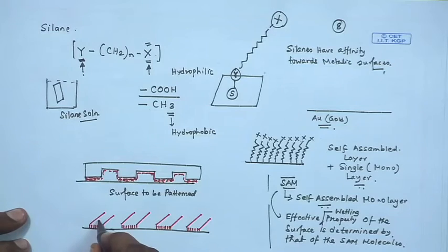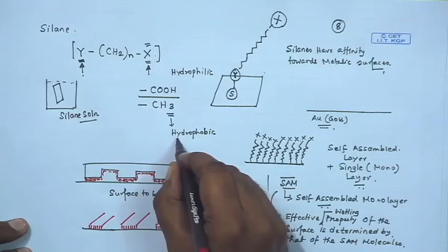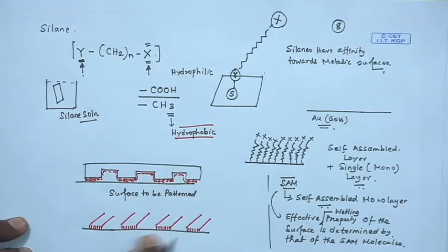Whether these silanized patches are hydrophobic or hydrophilic will depend on the nature of the silane molecule you are using. So, if you are using, let us say, a hydrophobic silane on a hydrophilic base, you can create a surface with alternating wettability domains. You can also start off with a hydrophobic surface and take a hydrophilic silane to achieve the same.